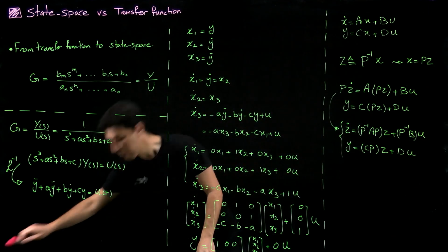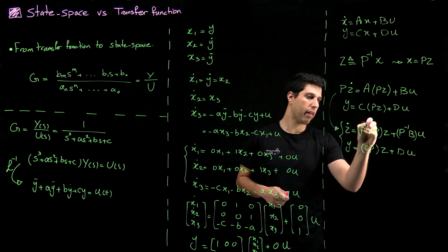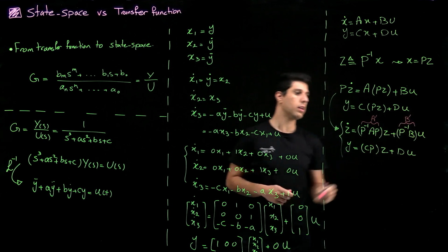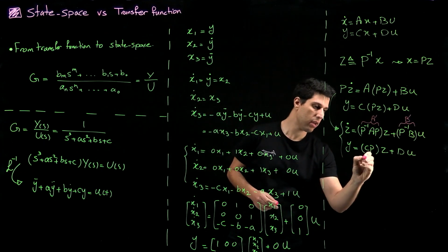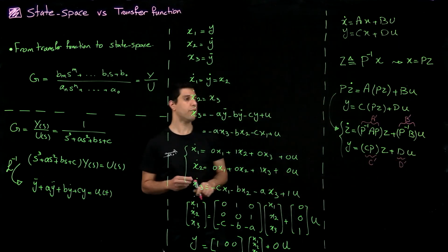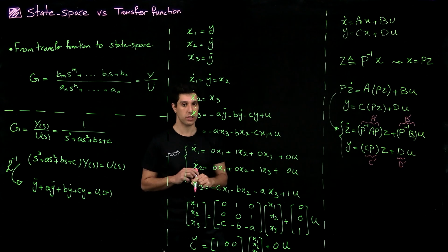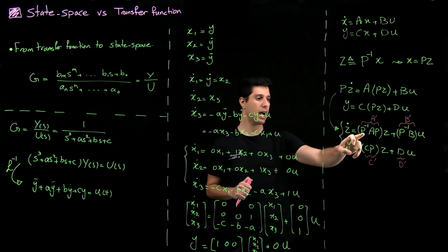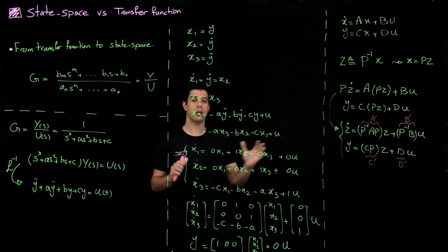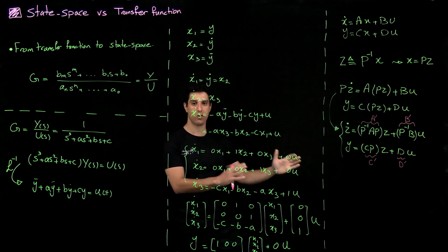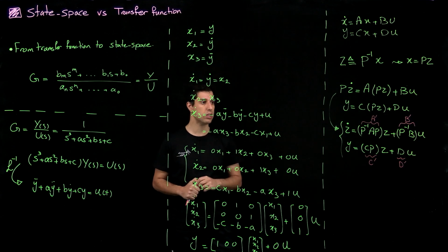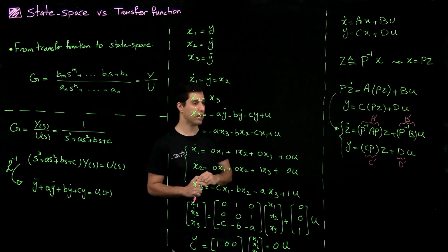Now essentially what I have done is construct a different state space equation where I have different A, B, C matrices, and well, D remains the same. So as long as I can find a P that is invertible, I can transform my state space from one form to any number of infinitely possible alternative state spaces that are all of them valid.